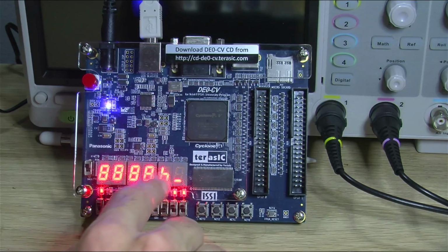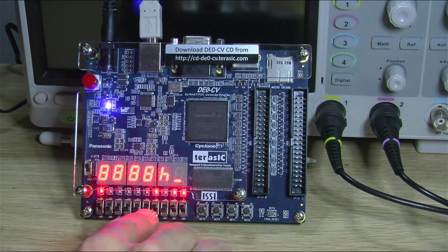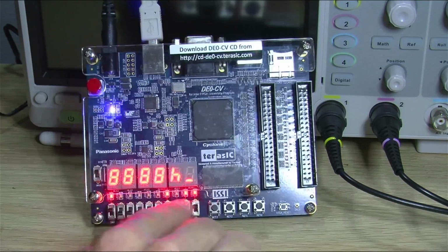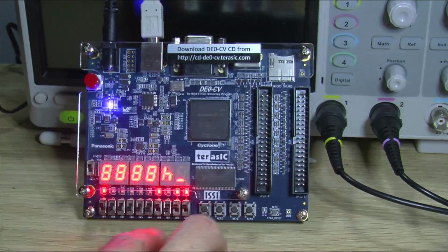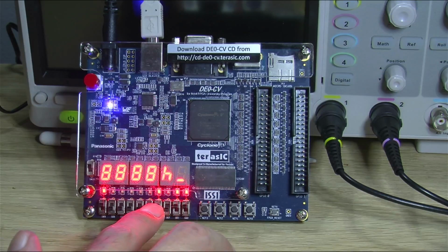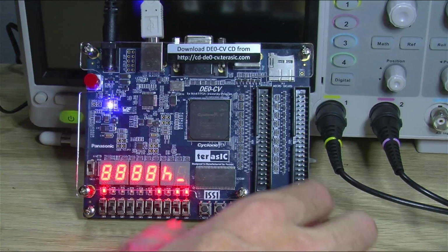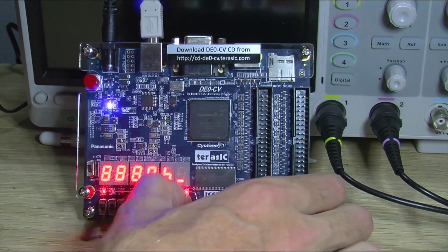And then this next digit, which is currently showing an H, is being controlled by the 7 switches down here on the right hand side. So there's 7 rightmost switches. Because we've got 3 of those switches currently turned on, we've got 3 of those segments currently turned off, which are the segments those switches are connected to.